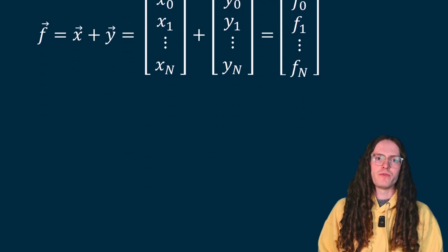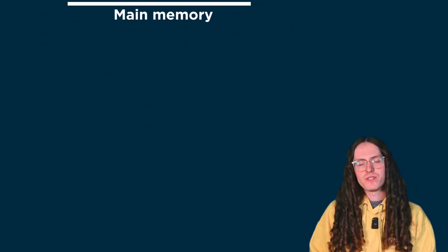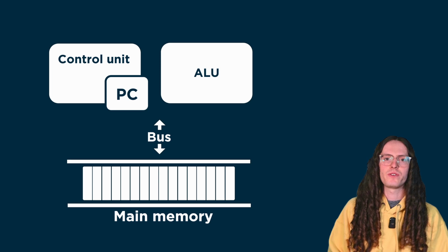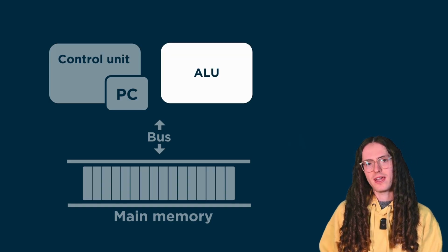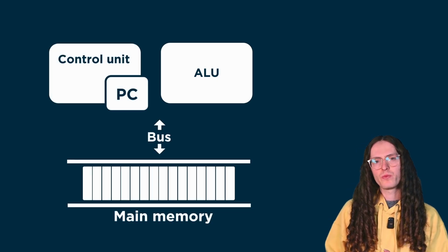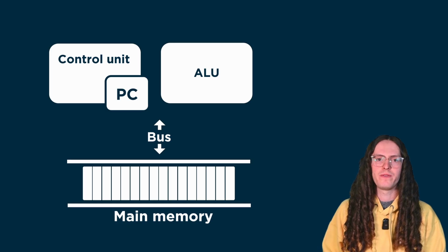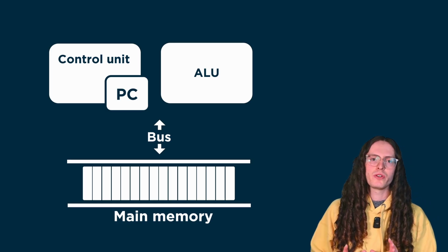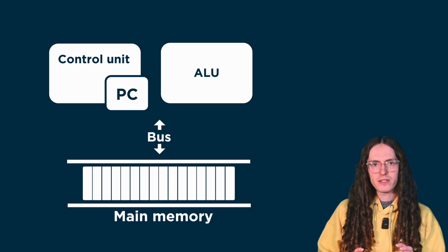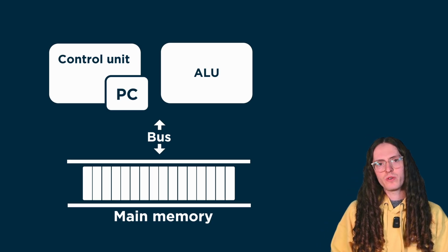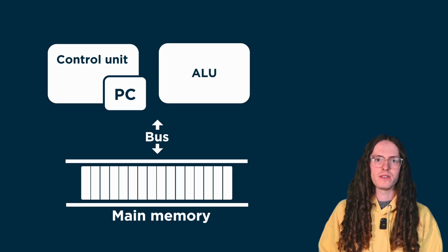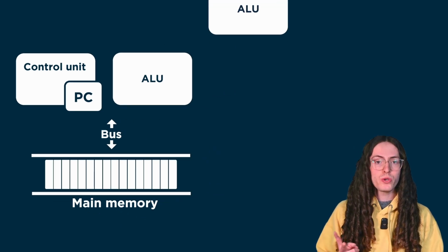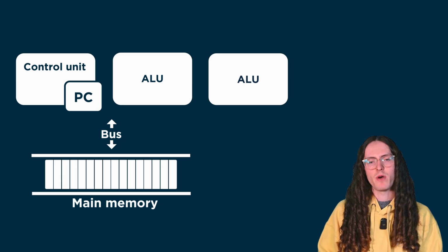To dive deeper, recall that a processing unit consists of several components. A processor has, for example, a controller or control unit and arithmetic logic units or ALUs, which perform the actual computations. There are other components as well, but let's just focus on these two for now. Now imagine our controller as a puppet master, which tells the ALUs what to do. We could also imagine this controller handing out orders to more than a single ALU instead. It could coordinate, for example, two ALUs both carrying out the same operations.